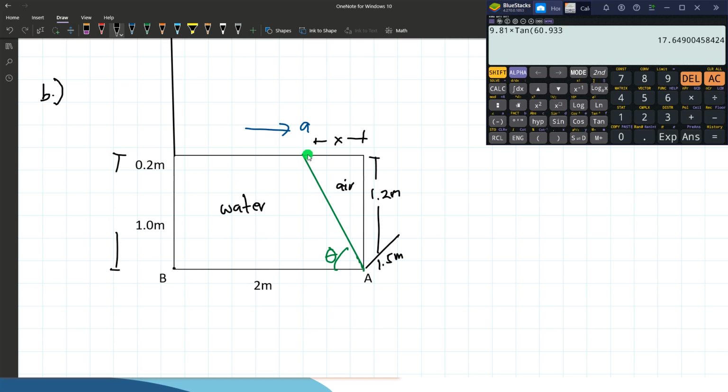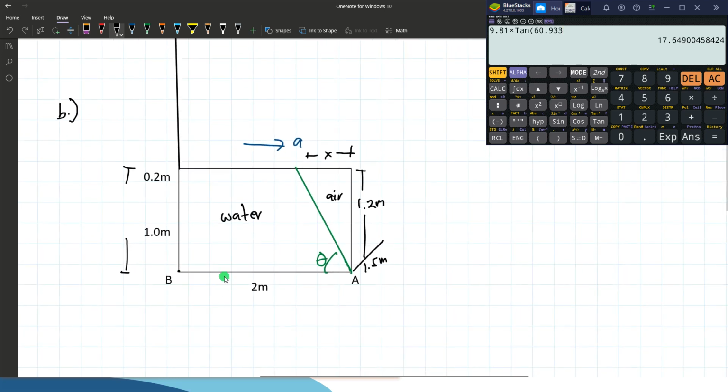But in closed containers that are moving, the pressure head at point B is computed by extending this liquid surface to the point where it will intersect the side, and extending also the side where we will find the pressure.